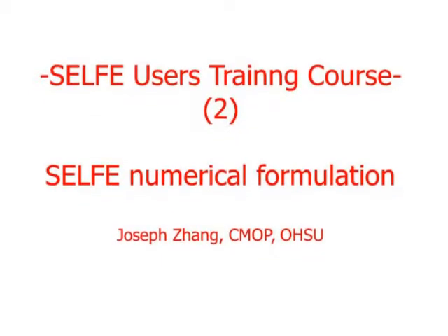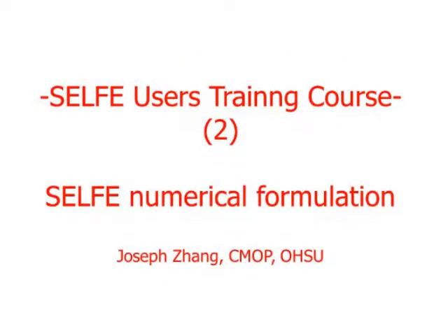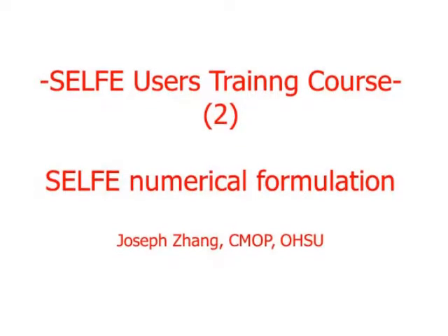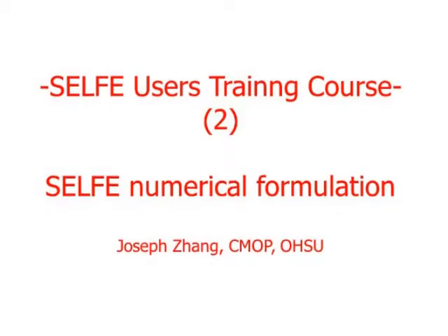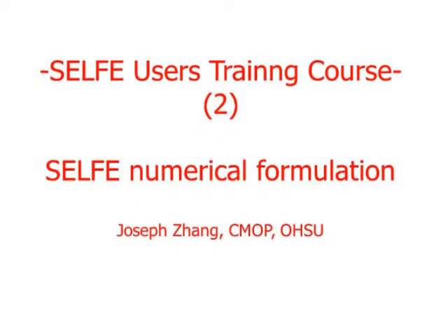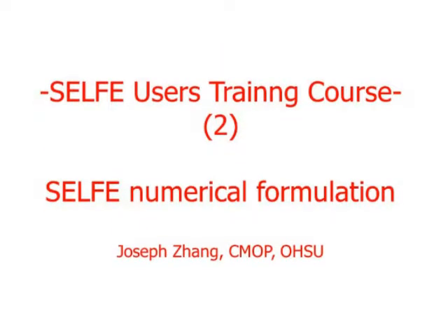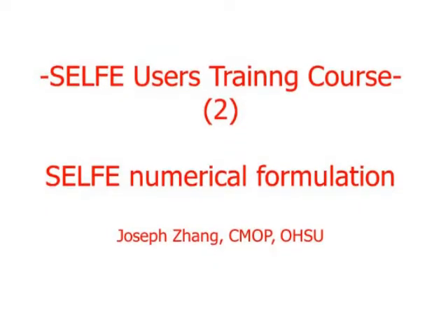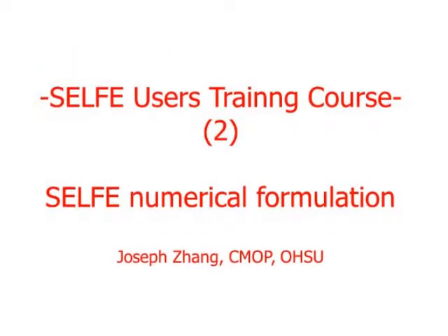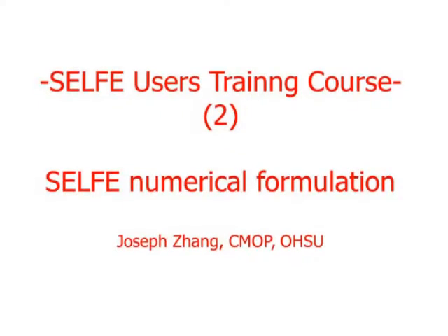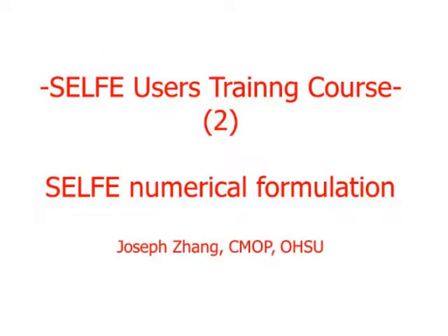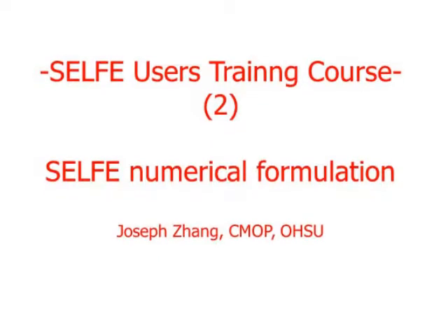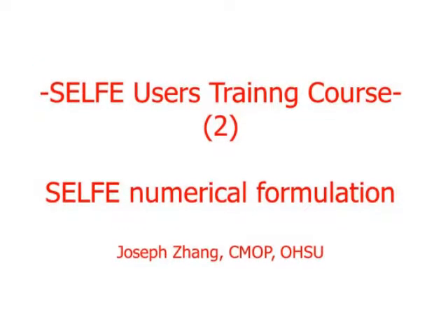Because you have to evaluate a number of integrals. And compared to finite difference methods, the bandwidth of the matrix resulting from a finite element method is usually larger. So in finite element method, sometimes people lump the mass to the central load, so-called mass lumping.